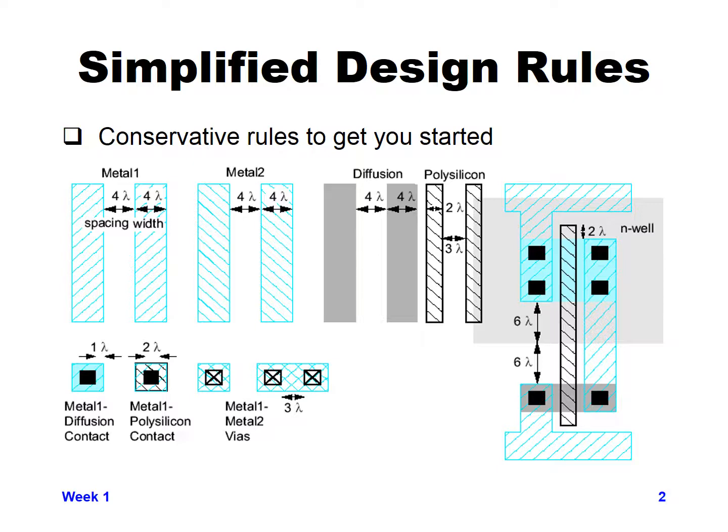The polysilicon, we already said that the minimum feature size is generally the width of polysilicon, which would be F, and F was defined as 2 lambda. So in general, the minimum polysilicon width can be 2 lambda, but if you have polysilicon routing next to another polysilicon in this process technology, it can't be any closer than 3 lambda apart.